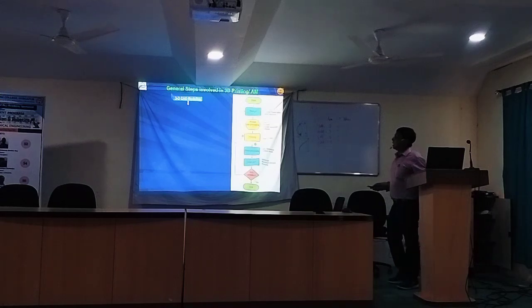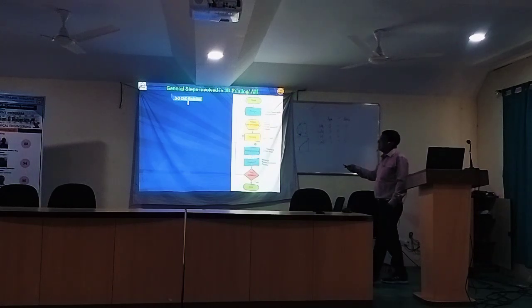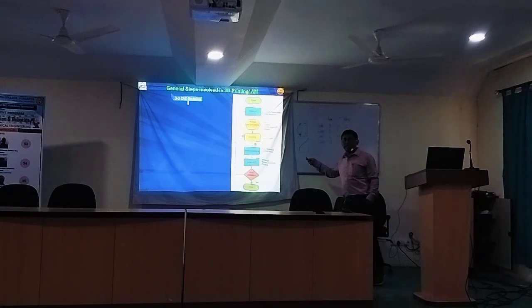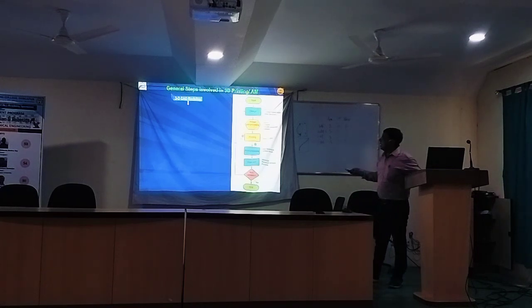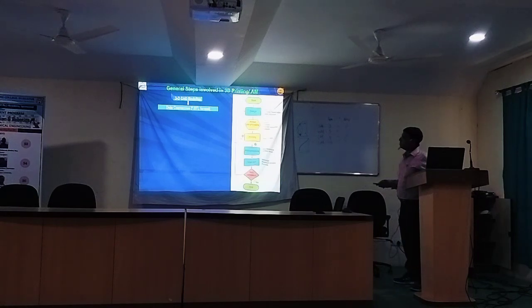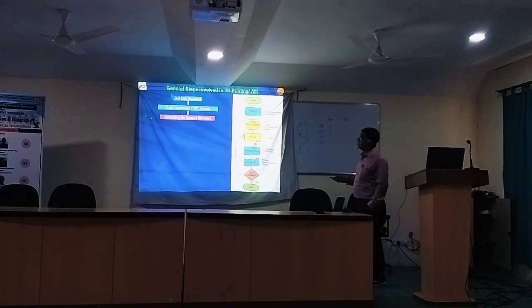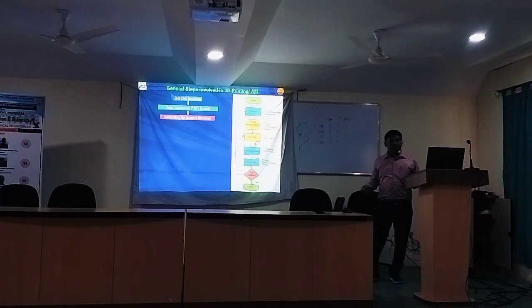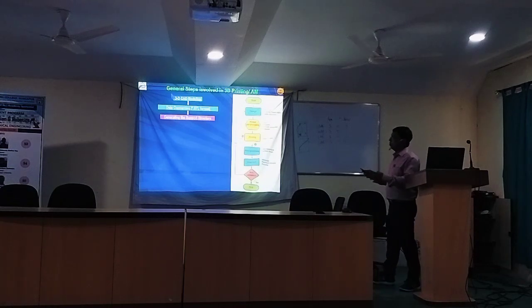Once you develop the 3D CAD model, you may do topological optimization and lattice structure design; these are now modern areas in additive manufacturing and in design. Then you have to save your file into a neutral file format, which is well accepted, the STL file format. That file will be imported by the slicing software, and before slicing, you have to orient your part, the geometric model, within that volume.